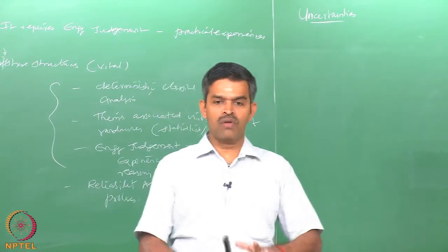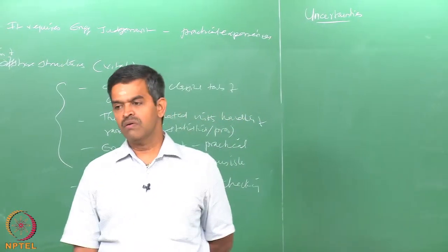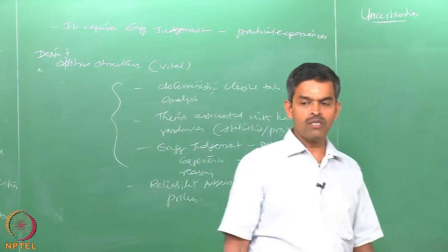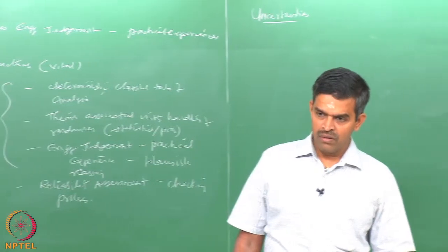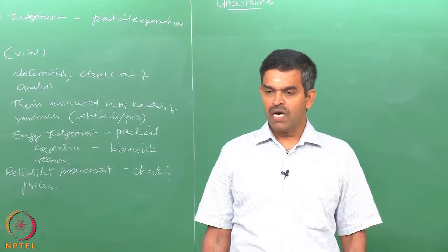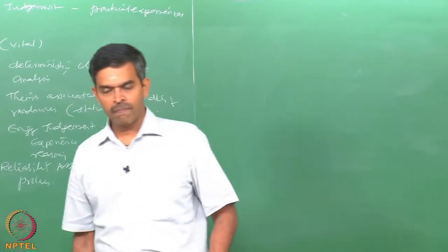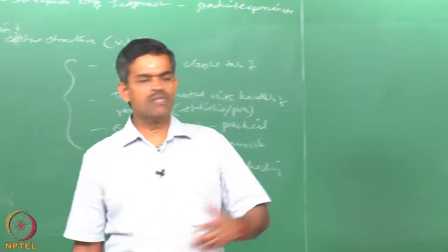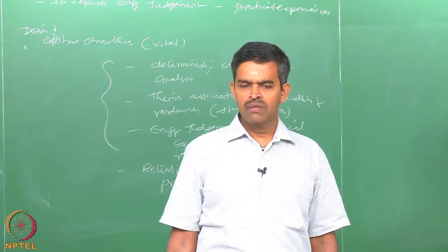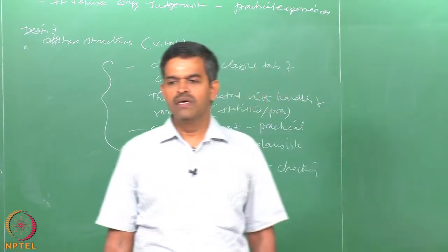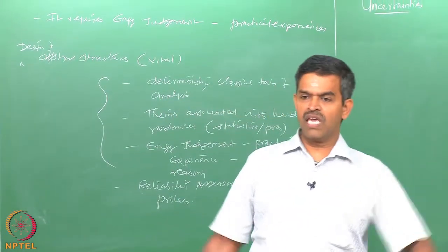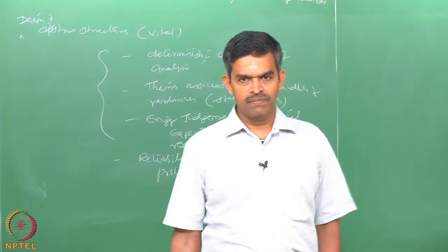I am not talking about structural failure at all, but functional failure, because failure in this case is defined very carefully as failure to perform the intended function adequately on demand over a period of time under certain specified conditions only. So, when we handle everything with certainty, then we need not bother about reliability at all, because it is not going to fail at all. Since uncertainties are inherently present in offshore structural design scheme, we have to talk about reliability.